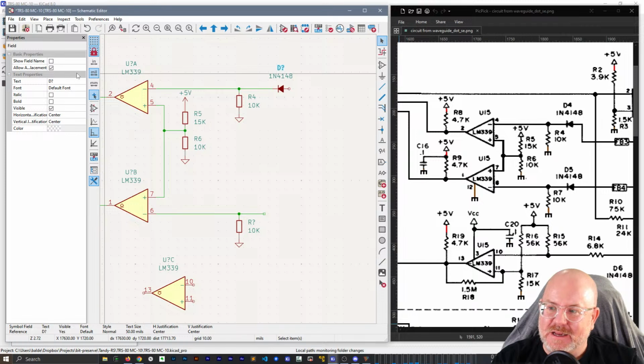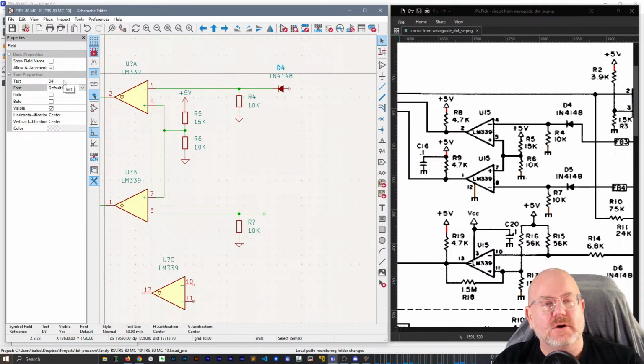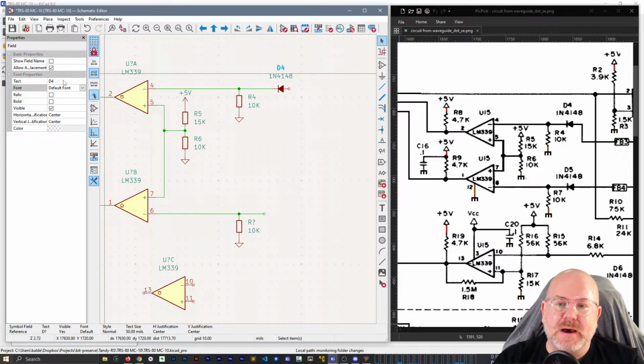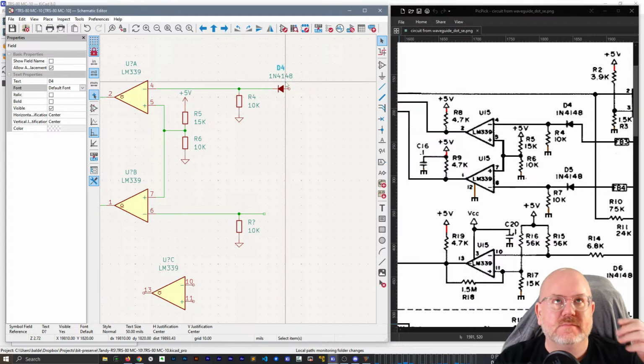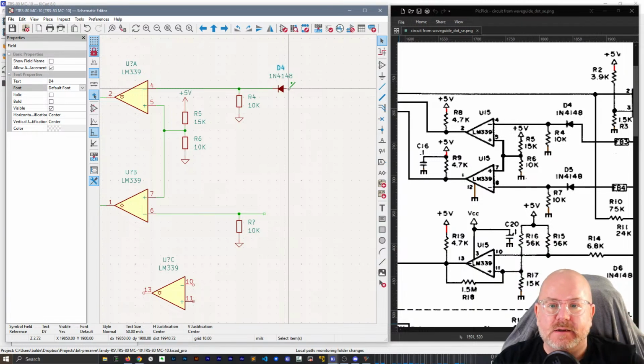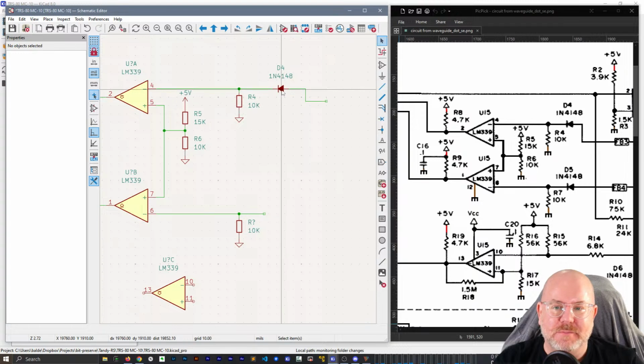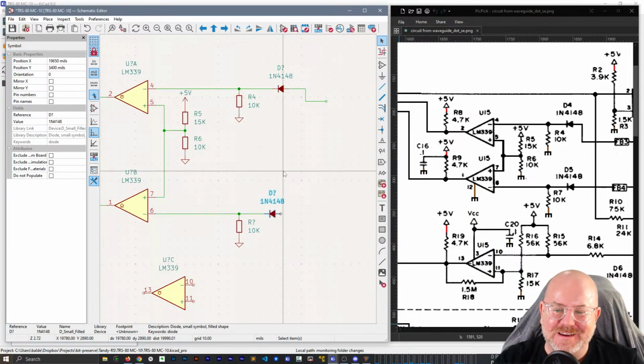Yeah, I spent 3 days in a row learning about Zephyr, the NRF SDK. I got examples working just fine on the development board. I moved them to a Seed Studio XIAO, which alone took me about a day to get to the point where it would compile. And the very first error I got, well, not first, because I had lots of errors to this point, but after the linker ran, the first thing it says is RAM exhaustion. I was like, wait a minute, what? Come again? That's not good.